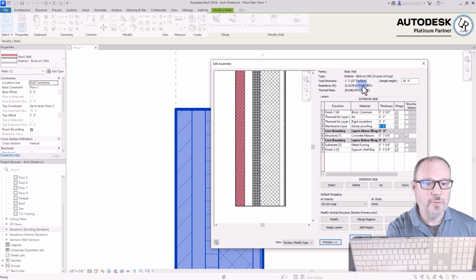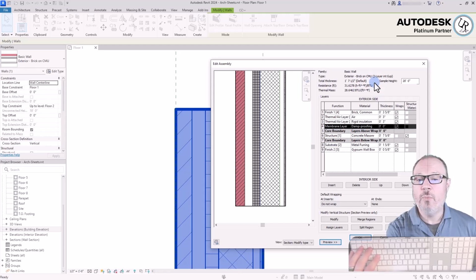And even though this material doesn't have an applied thickness attached to it within the wall's construction, it will still be helpful to include that because of 2 reasons. The material takeoff that Revit can establish for you, this material could be included in that material takeoff, so that it would want to be included for that purchasing order in that list of material. Also, Revit has the capability of running an energy analysis, and with that material included in the wall's construction, it will benefit the wall's analysis with that material intact. So you would want to include any materials that are part of the wall's construction in total.